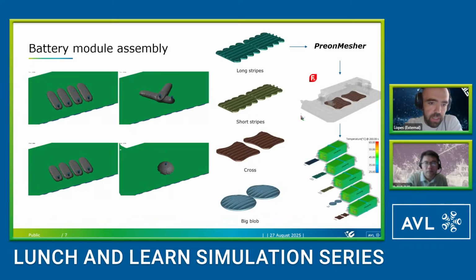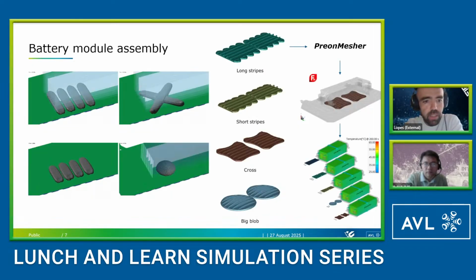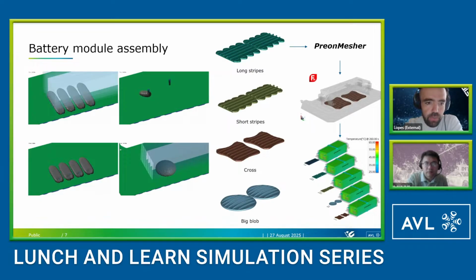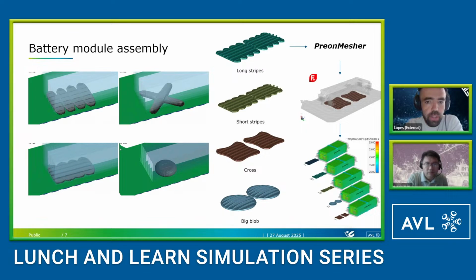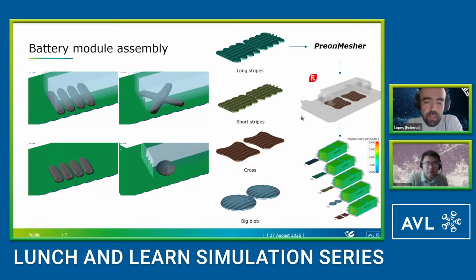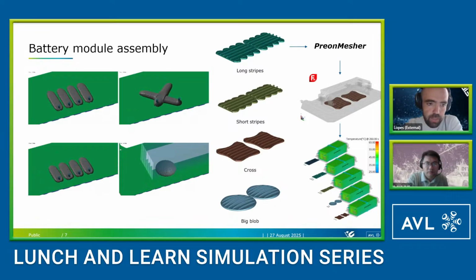And we see here the study that we did was to inspect the different initial depositions of our gap filler, of our thermal paste, and with the pressing of the battery, we want to infer the different geometries at the end of the simulation and get in this way to know which is the better geometry that can provide the highest heat transfer for my setup.